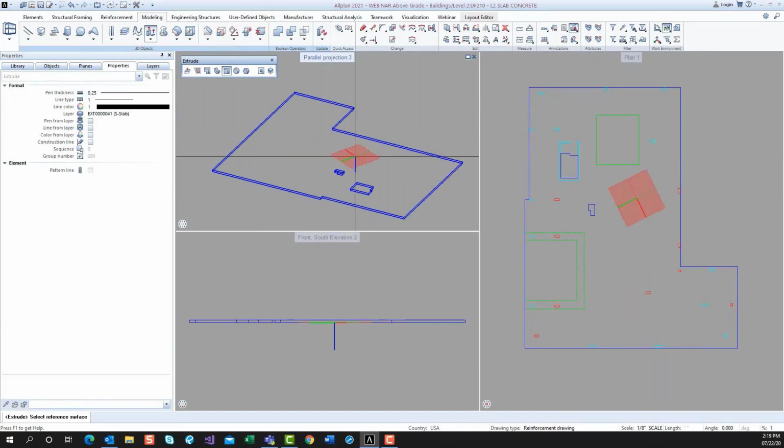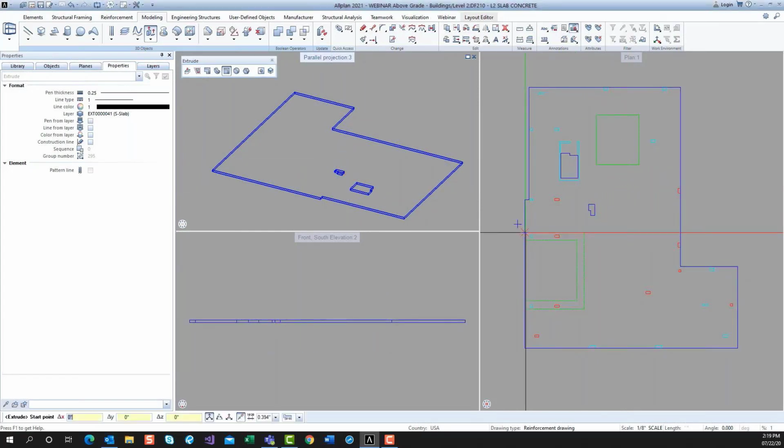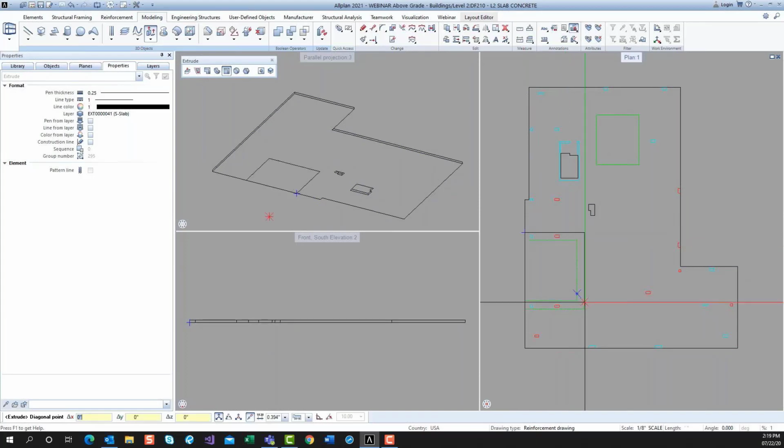You'll notice as I'm zooming around here, just to show you, as I move around, it's telling me which face my extrusion is going to start on. So in this particular case, I'm going to create my step on the bottom of this first. So I'm going to select the bottom face of this 3D object. And then by simply picking on points on my polyline, it now knows I want an extrusion.